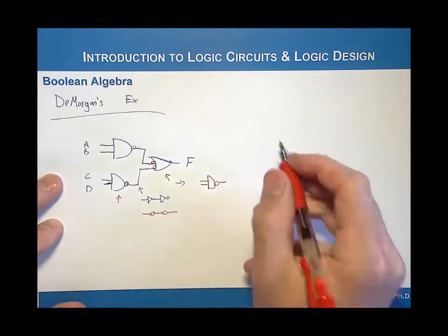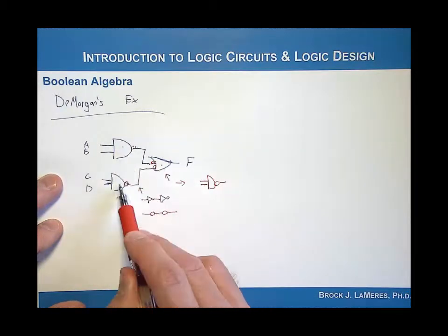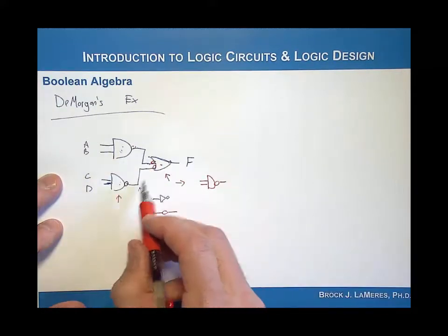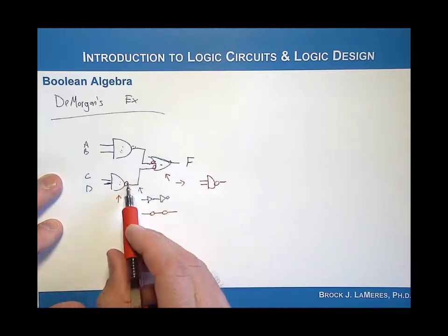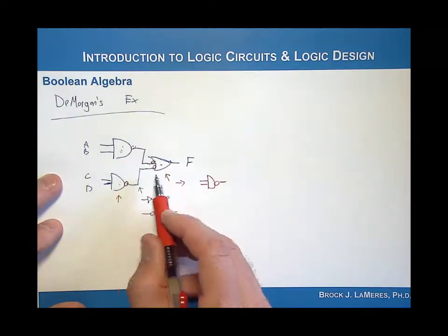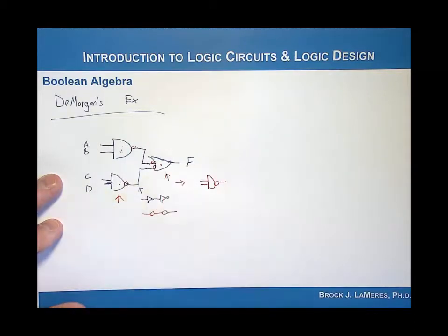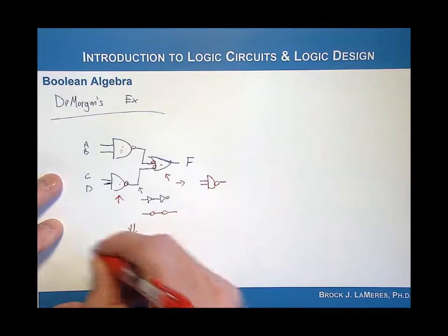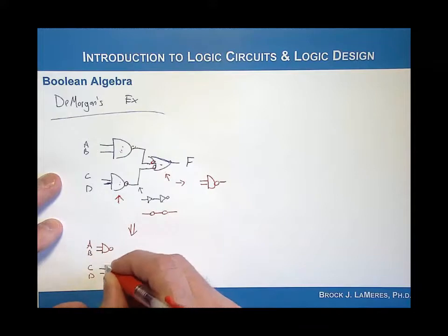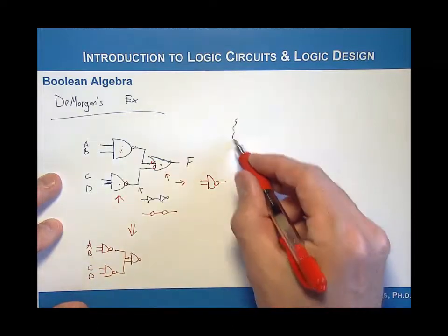Anytime I see one of these, what we call a sum of products, where I have an OR gate that's fed by two or multiple product terms, I can directly convert this into NAND gates by first performing a double bubble using the involution theorem on these internal nets. Then I have inherently converted the product terms into NAND gates, and I use De Morgan's to flip the sum term into a NAND gate also. So this directly goes to A, B NANDed together, C and D NANDed together, and then the entire thing NANDed together. So that's a very practical application of De Morgan's.